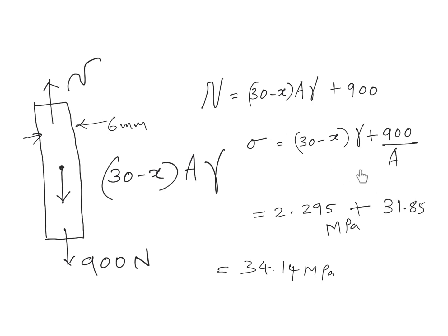You know the specific weight of steel. For the density of steel, you can assume a value of 7,800 kilogram per meter cube. From this you can calculate the specific weight, and you can plug in those values right here in this equation. And in the problem it is given that the bar is of diameter 6 mm, so area can be easily calculated using the expression pi by 4 d square. Once you add these two things, then from the self weight, let me explain it completely.